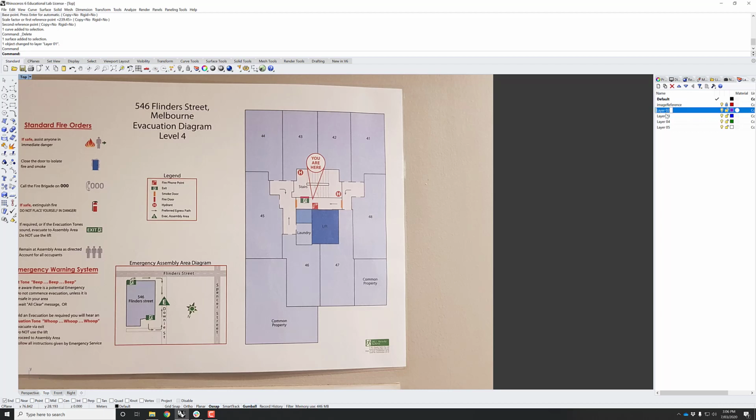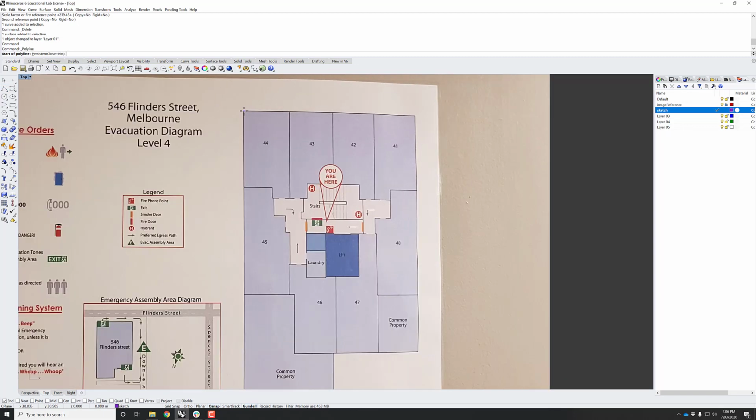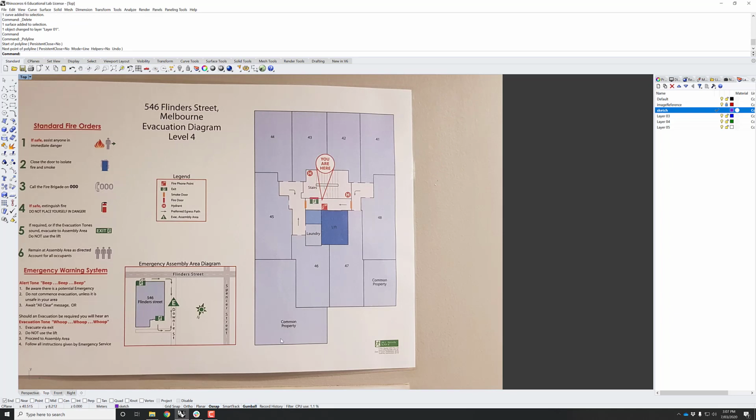We're going to go to layer 2. Just want to create a sketch layer, so I'm just going to use a polyline over here. If I hover over here, we left click. So let's try and not miss some of the nuances of how I've set this up. There's an ortho snap down here, and if you can't see these, you can right click.